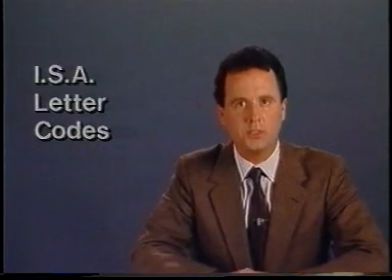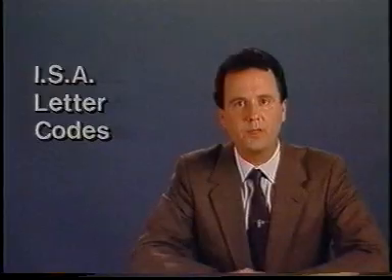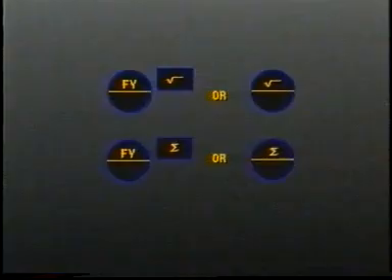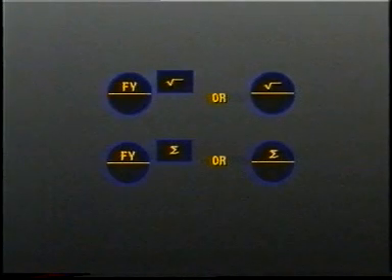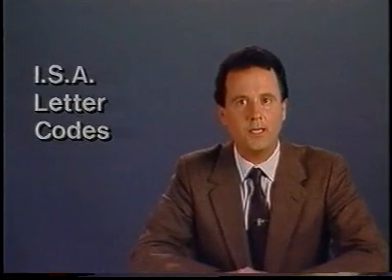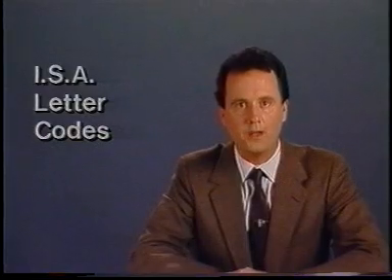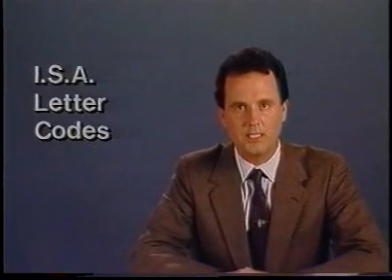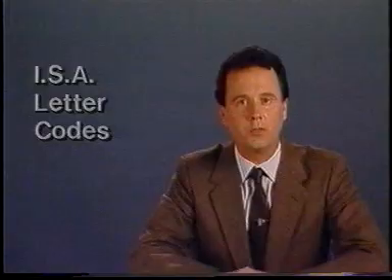As you familiarize yourself with the ISA letter codes in the student guide, you'll probably become aware of the fact that there are often several ways to express the same computing function. The important point to remember is that the symbology elements within a circle are there to communicate to the person reading them that the indicated computation must be performed at that station. As long as that computation is adequately communicated, the choice of symbols is not important.